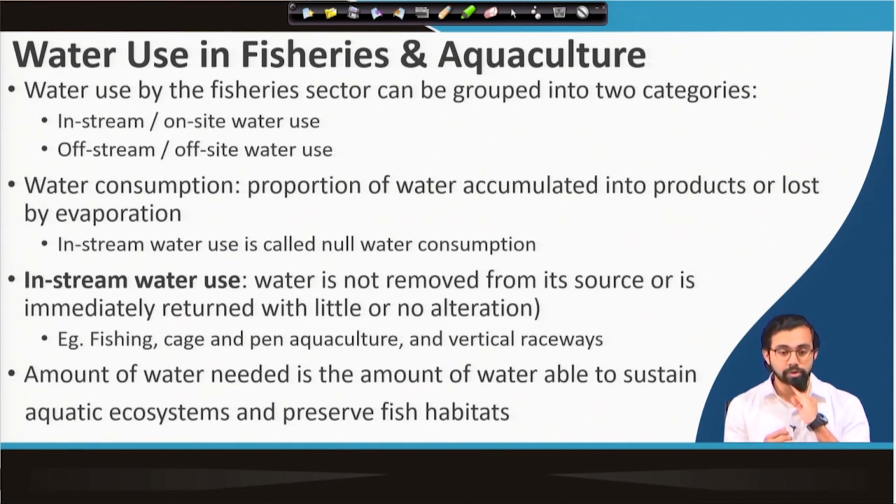Because the pond or the tank that you are using has a high surface area. Because of its high surface area, because of the sunlight and the normal wind movement, the water evaporates to the atmosphere. The water keeps on evaporating to the atmosphere, and we call it evaporation loss. Okay, so this evaporation loss is one of the major losses in any kind of pond.